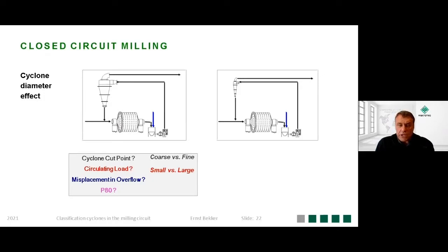And you've got water addition, sump level control, fixed speed pump. As you start to reduce the circulating load, the amount of material that will report back to the mill from this big cyclone, you need to add more water to keep the level. And thereby the feed density reduces and the cut point becomes finer and the circuit will then restabilize.